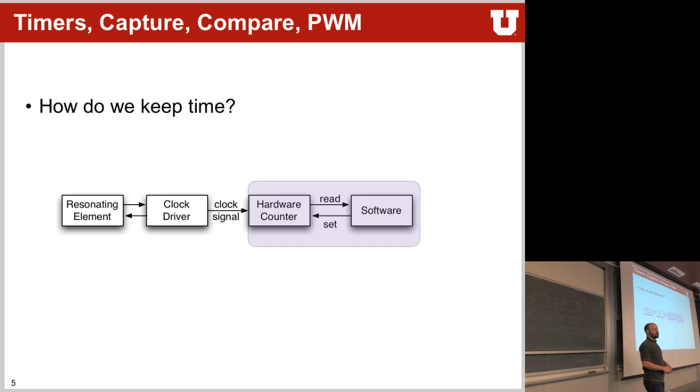Whenever this and this matches. And there are lots of different options there. Sometimes you can have a set only, sometimes a reset only, or a set reset, reset set, etc. Yet again, it can be a very complicated thing, but the principle of a compare is always the same. It's a value that you write in software into that register, and whenever that register matches with a counter, something will happen. An action will be taken.